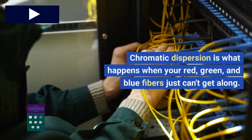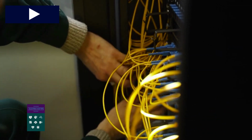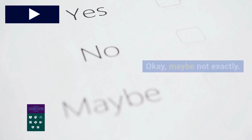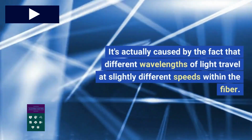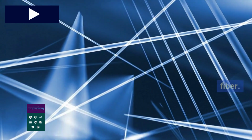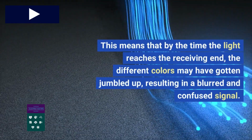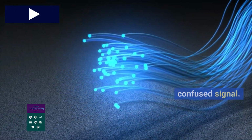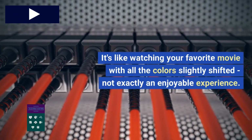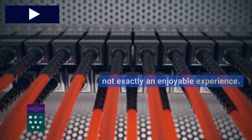Chromatic dispersion is what happens when your red, green, and blue fibers just can't get along. Okay, maybe not exactly. It's actually caused by the fact that different wavelengths of light travel at slightly different speeds within the fiber. This means that by the time the light reaches the receiving end, the different colors may have gotten jumbled up, resulting in a blurred and confused signal. It's like watching your favorite movie with all the colors slightly shifted, not exactly an enjoyable experience.